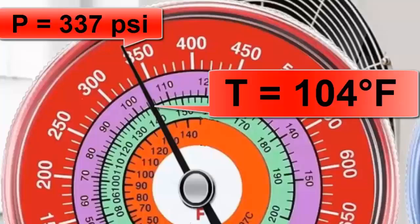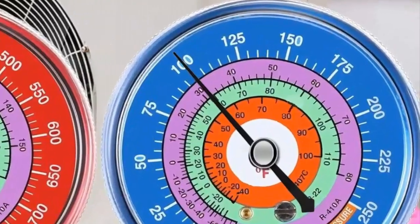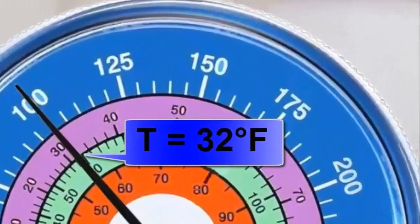Now let's review some faults detected using gauges. A. If the indoor coil is freezing, the temperature drops below 0 degrees Celsius, 32 degrees Fahrenheit, and the low side pressure is expected to be below 100 psi.